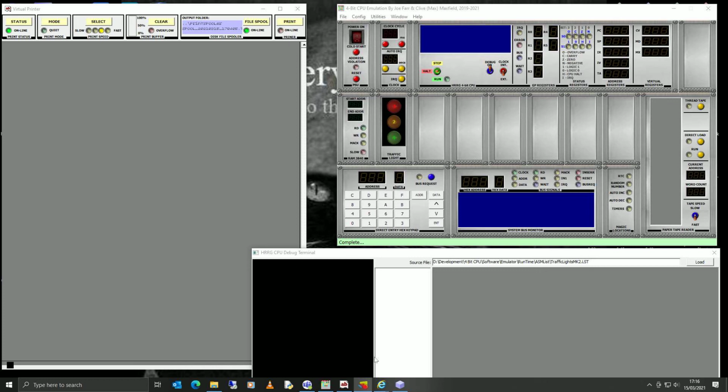This at the bottom here is a debug terminal that the CPU, this module here, gives us if we want. We can interact with the CPU, so interrogate registers, the status registers, change bits in the status register, dump memory, fiddle with the register values, etc. This section here will show us the instruction pipeline and the nibbles that the instruction is loading from memory.